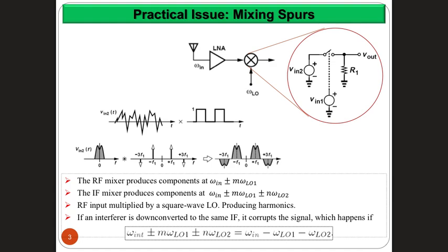And the other thing is, based on this, we know that mixers you can think of as a kind of noisy component. It's not noise here, but it's distortion. So they are components that introduce a lot of distortion, and they are one of the hardest parts of your RF transceiver to design.